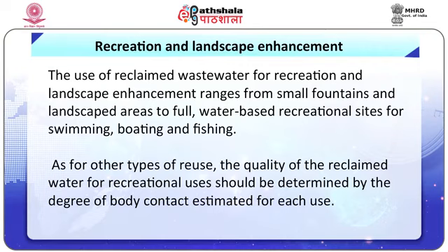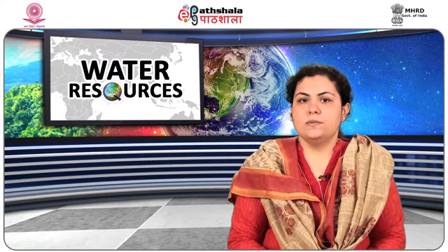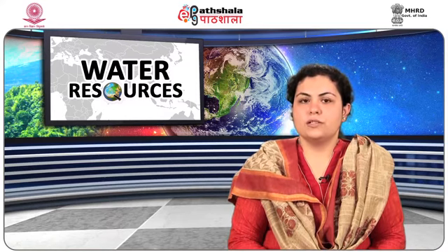Recreation and landscape enhancement. The use of reclaimed wastewater for recreation and landscape enhancement ranges from small fountains and landscaped areas to full water-based recreational sites for swimming, boating and fishing. As for the other types of reuse, the quality of the reclaimed water for recreational uses should be determined by the degree of body contact estimated for each use. In large impoundments, however, where aesthetic appearance is considered important, it may be necessary to control nutrients to avoid eutrophication.